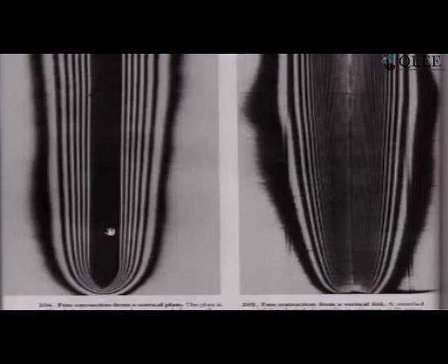So here what we are seeing in both cases is a technique called interferometry. That's what you might have come across in physics, that if you have two beams going in and one is deflected, then at the point where the two beams join, there will be constructive and destructive interference. So you will see dark and bright lines. So that's what has been done here. The equipment that is used is called a Mach-Zehnder interferometer, and you have put a laser light in it, and another part of the light without going through the domain comes out, joins up with them, and it produces these fringe patterns. So what you are seeing are interference fringes.